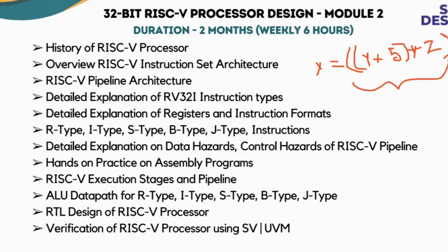We will have one table format, right? So what is meant by an instruction format? For every format, suppose you take an I type or J type, whatever, it has some format. What is the source register and what is the destination register, and it has some opcode and offset addresses. Based on that, it would convert into the binary value. That binary value would be understood by the RISC-V processor. So this is what is happening. For every stage, I will show you more clearly.